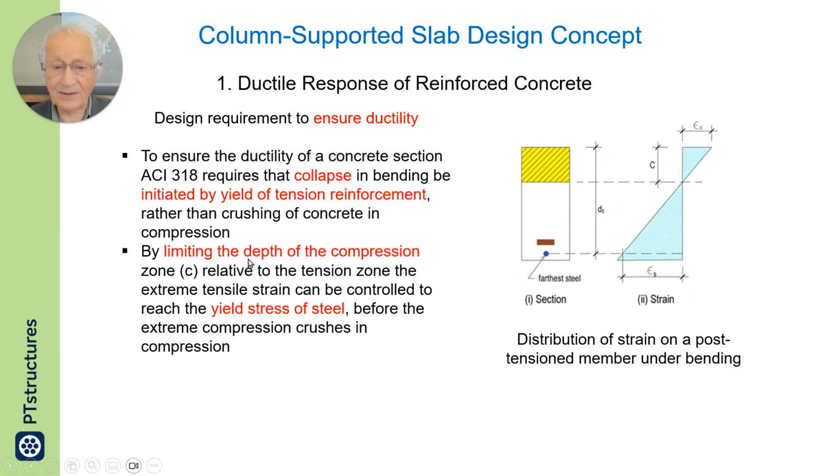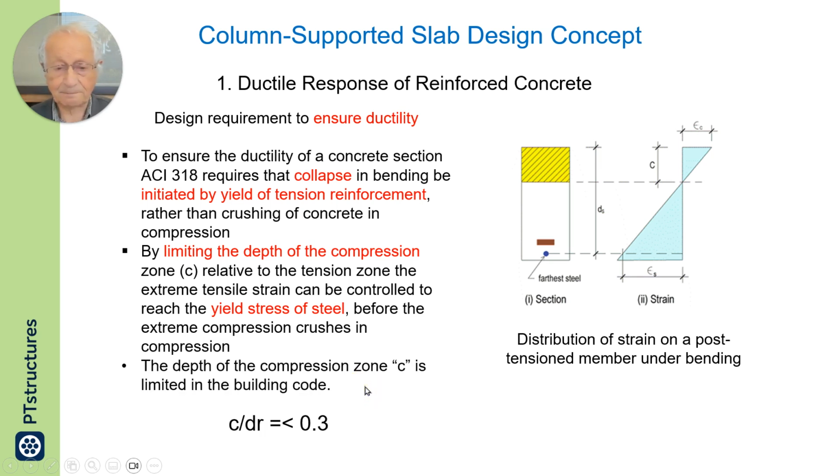By limiting the depth of the compression zone relative to the tension zone, the extreme tensile strain can be controlled to reach the yield stress of steel before the extreme compression crushes the concrete.